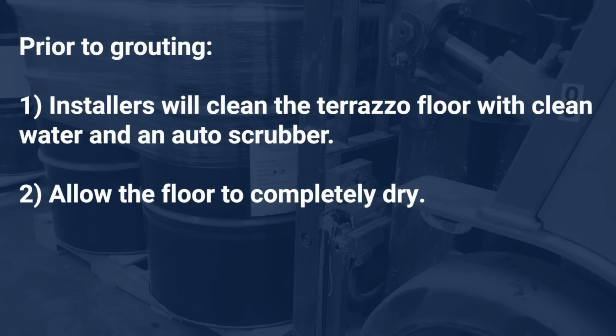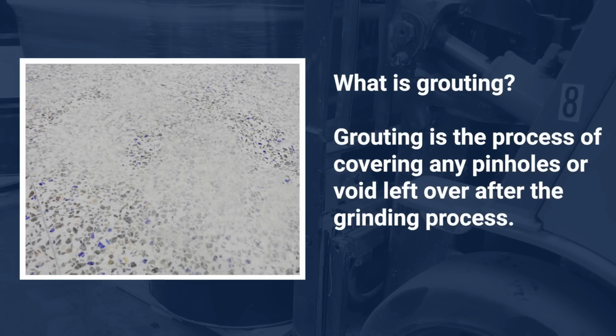After this stage, it is time for grouting. Installers will clean the floor with water and a scrubber and vacuum the floor completely dry. Grouting refers to covering any pinholes and voids left after the grinding process. Installers will apply a small amount of epoxy matching the floor color, covering up these pinholes.